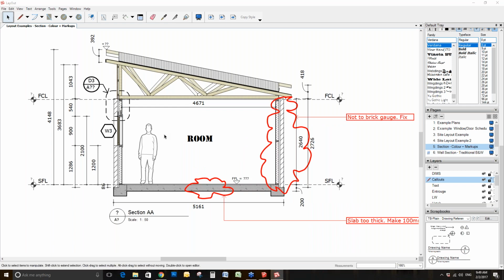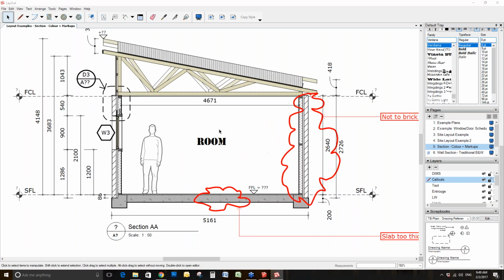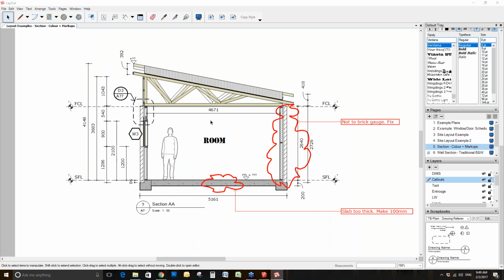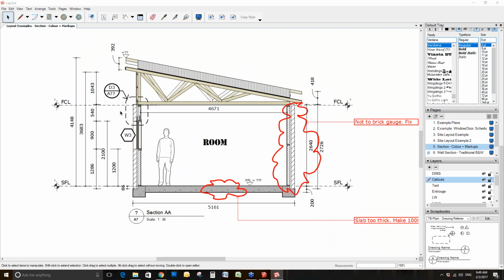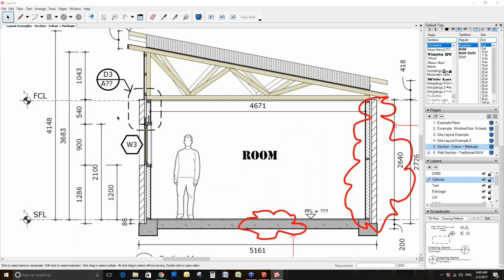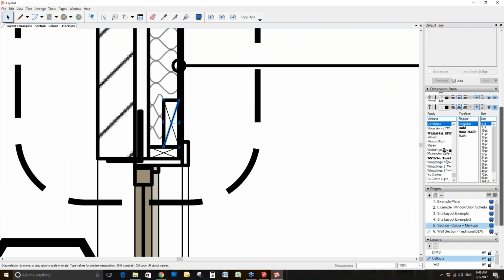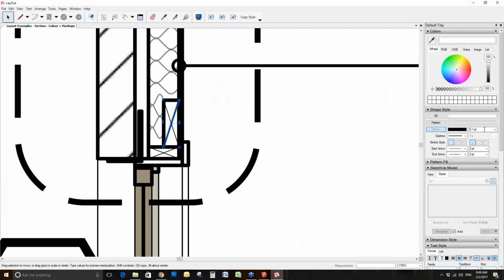So, quick example. Again, the most important thing here is that all of the work's been done for me inside of the section that I did inside of my PlusSpec for SketchUp model. However, I have put in a little line work just to ensure that I'm capturing it and it's reading the way I want it to read. Setting the line weight by going into my line tool, in your stroke you can set the stroke, you can set the line weights, you can set the line styles, and so forth.